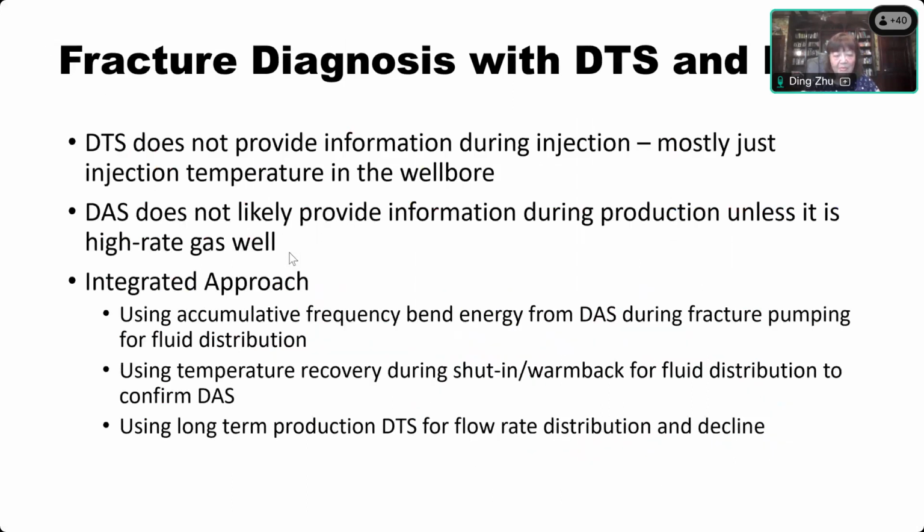Now the situation becomes much harder if I actually want to do interpretation of a current fracture design. We changed it from 15 stages, 4 clusters per stage, to maybe hundreds of stages, like 4 to 12 clusters per stage. So we fracture our formation much harder than before. Now, a single interpretation cannot even provide the correct understanding of today's treatments. So the next step we came up with is to combine the measurements. These could be temperature measurements, DAS measurements on sound, pressure, vibration, low frequency DAS on fracture hits, on strain change, on stress field.